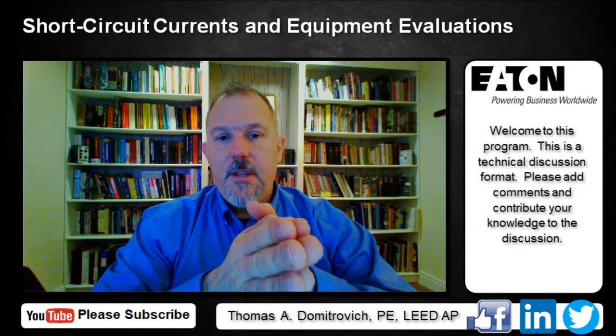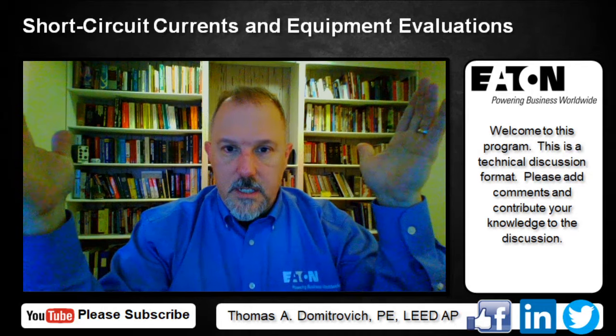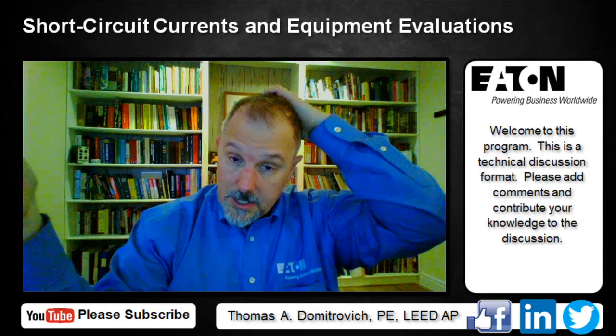Always check. A lot of people say, well, I have all these appliances in my kitchen, and all of those are going to add up and trip my GFCI protection if I put it in the circuit breaker. The reality of it is most of your appliances only have 2 prongs. That's because they're double insulated and they have other provisions in place, but you can't have leakage current if you're only using a hot and neutral. The moment you have the equipment grounding conductor, now I can have leakage current over that equipment grounding conductor. So anything that has a 3-prong, I could have leakage current.